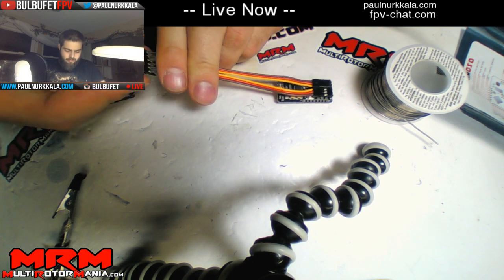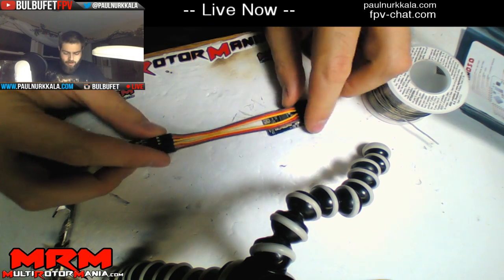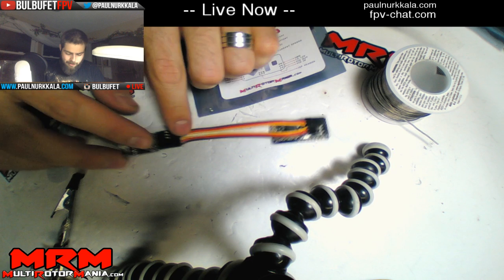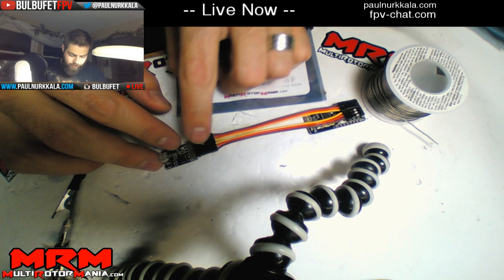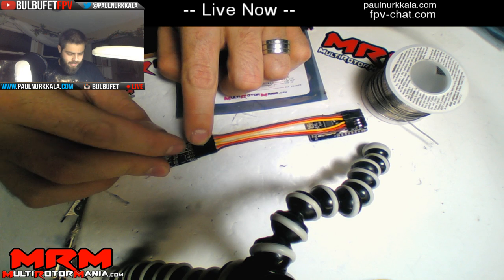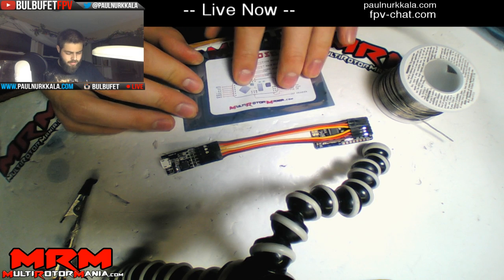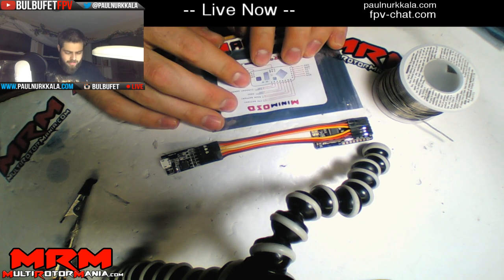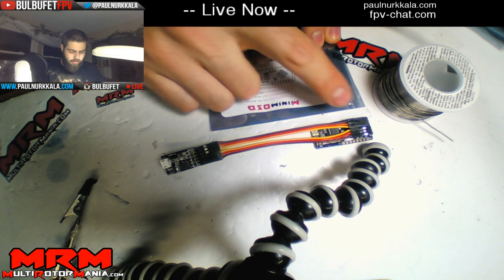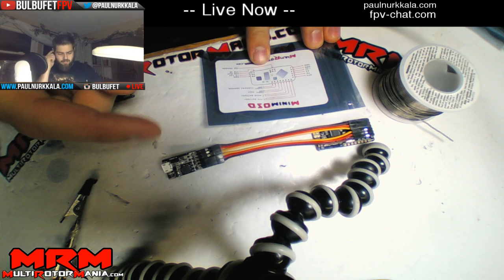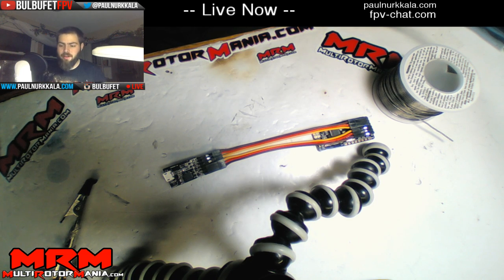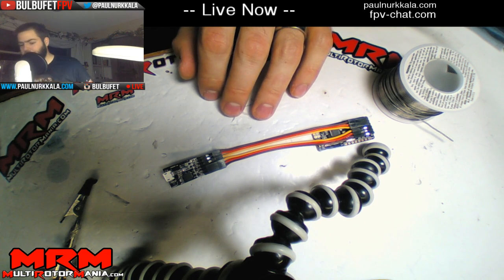Jeez. So on this side, you probably can't see it on the camera, but you have ground positive. And then on this side, looking at this diagram, you have ground positive. And so that's this cable going across, and that polarity is correct. So you just always want to make sure before you plug it in to 5 volts on the computer.